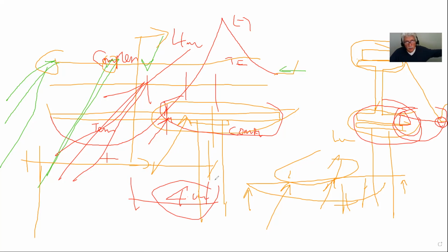Instead of it being 10 meters, you can reduce it down to 4 meters, because you will be specifying on your drawing to add a knee brace at that joist. So on your drawing, you're going to show all your members. You're going to have your column here, and then you're going to show your open web steel joist.